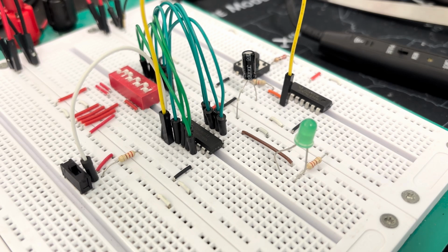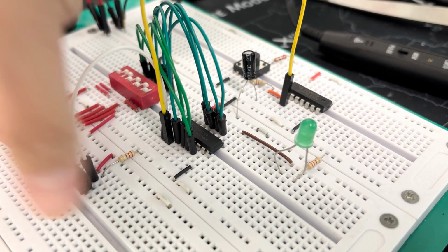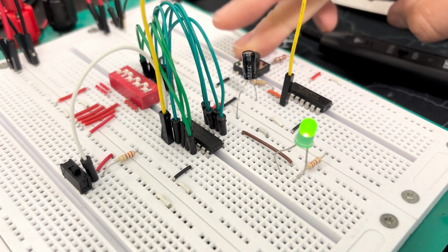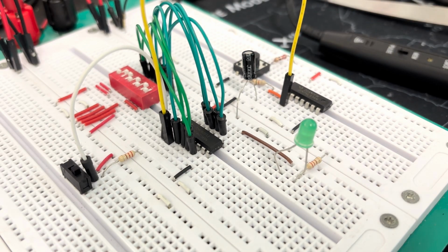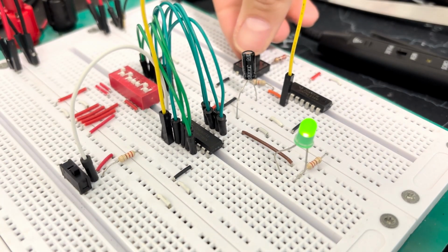I used the same data as the last example, in hexadecimal 0x6a. I select load by sending a low signal to the load shift pin, and press the clock button to load the data into the register. Then I select the shift function by sending a high signal to the load shift pin, and can clock that data byte out. I repeated this with the data byte represented by 0xA2.